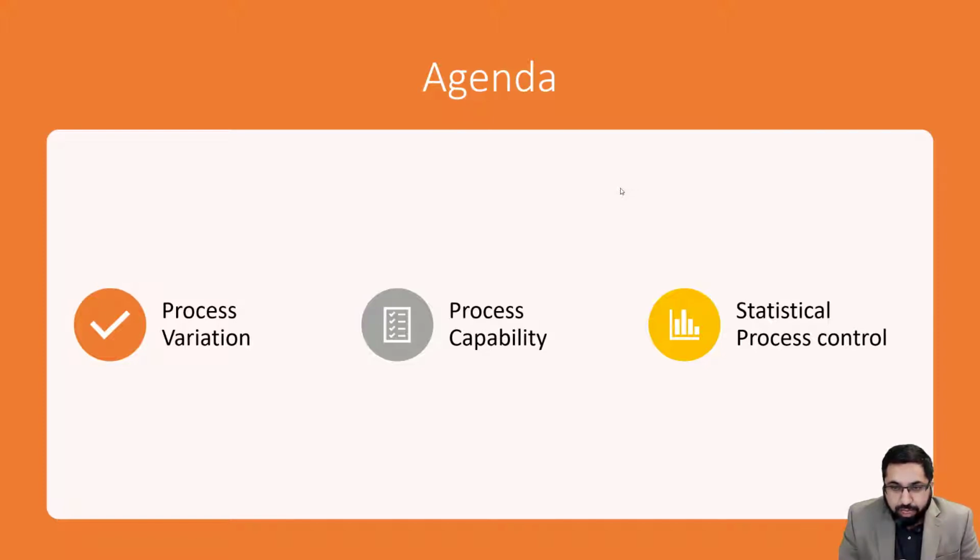And then once you establish through process capability calculations that a process's output is going to be useful and meet customer specifications, then it makes sense to control this process, because you want it to continue to meet customer specs. So that is why I believe the more logical order is to study process capability and then study statistical process control.